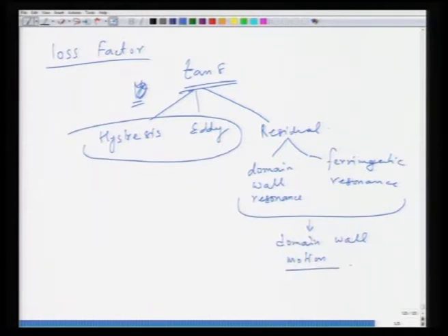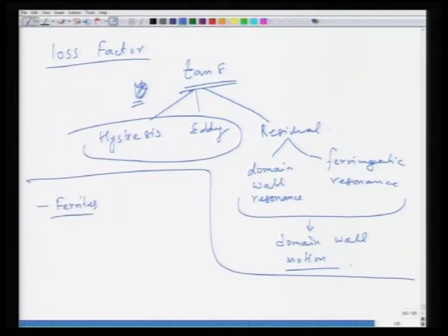Okay. Now, in case of ferrites which operate at high amplitudes, and high amplitudes would mean anything in excess of 10 millitesla. 10 millitesla is quite a high amplitude of field, and frequencies of the order of 10 to 100 kilohertz are typical.